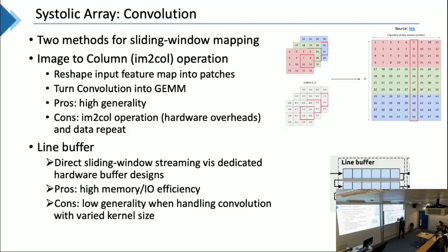You choose to output the data from the first memory line buffer to the next line buffer. Which means when more data comes in, the 1, 2, 3, 4 will move to the next line. For example, 1, 2, 3, 4, and you will have 5, 6, 7, 8 in the first line buffer, because the data keeps streaming.